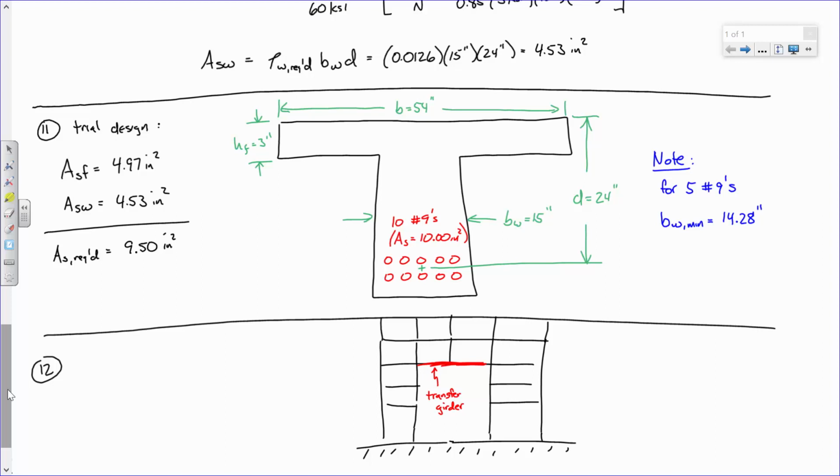Okay? And so that transfer girder is basically seeing like a column load directly on it. So this girder sees a lot of shear and a lot of moment. It's going to be a very specially designed element in the system. Whereas the 800 beam elements in the building that are just floor elements like here, they're just going to be regular old everyday beams.